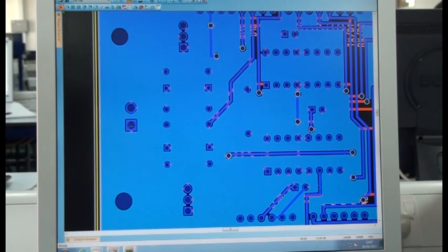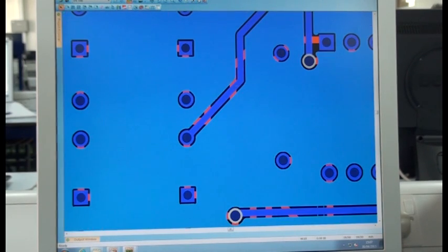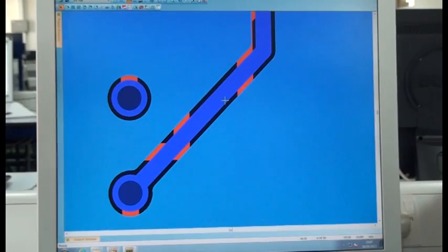So they have these little spokes, and thermal reliefs is their name, which reduces the likelihood that the heat will escape through these little spokes. And so the temperature of the actual soldering iron will be high enough to be able to melt the solder. And obviously anywhere where there's a track that isn't ground, it puts this isolation.